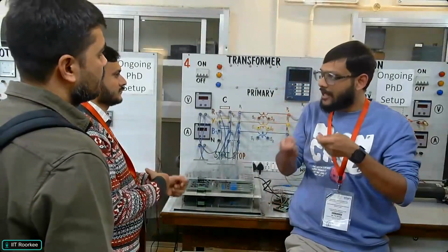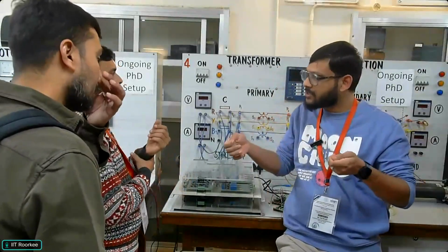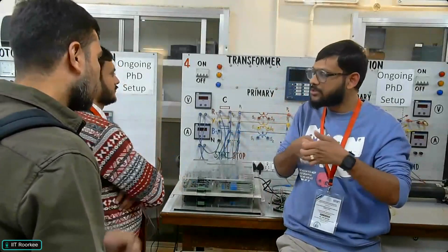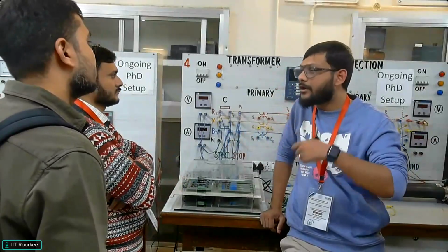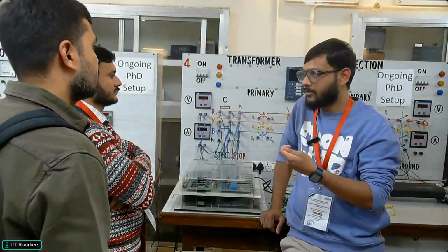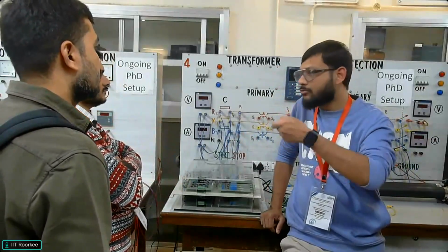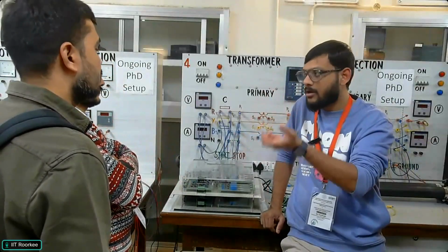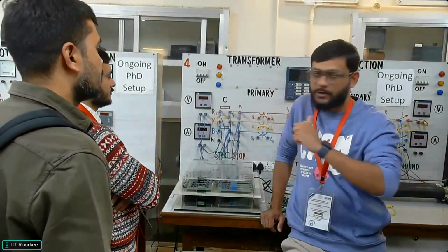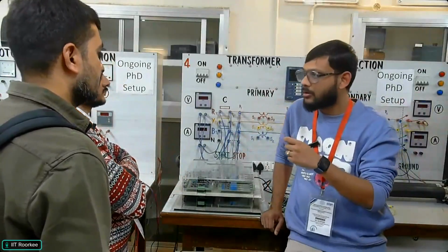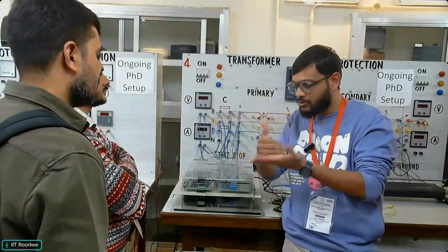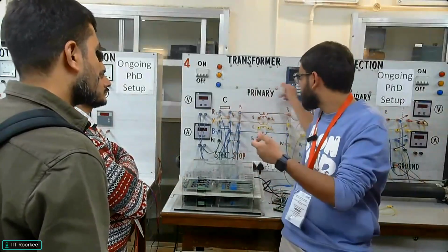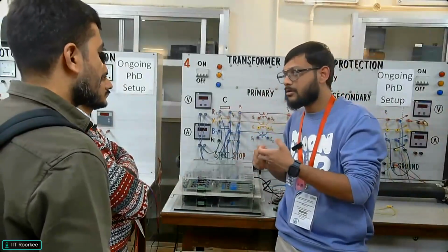This relay will have LAN connections. Multiple buses will be there. You can connect to the Ethernet switch and it will go to the relay. Instead of sensing current, it will now get a digital signal from the Ethernet. The algorithm will be the same, and the decision will be transferred to the circuit breaker using the GOOSE protocol. That automation we will discuss tomorrow, how GOOSE and everything will be interfaced with this type of relay, SEL relays.